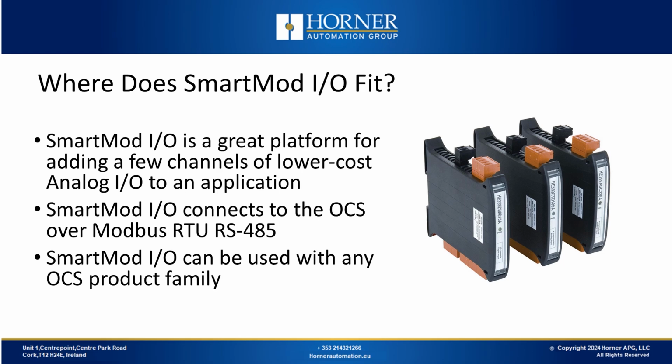SmartMod is an ideal platform if you just need to add a few channels of lower cost analog to your application. SmartMod I/O connects to the OCS over Modbus RTU, and every OCS supports Modbus RTU, meaning you can use SmartMod with any OCS product family.